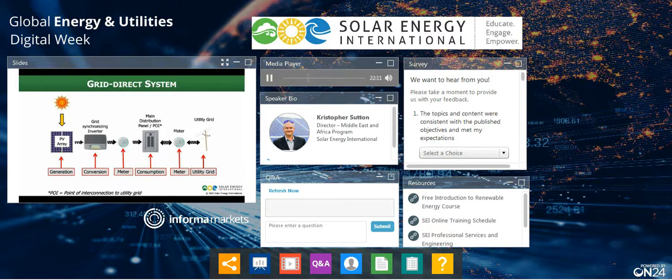The next thing that happens, we go DC from the PV array into the inverter. The inverter, when it sees AC electricity from the utility grid, will synchronize with it automatically. Once it synchronizes, which can happen in seconds because it's electronic synchronization, this is completely different than trying to synchronize a motor generator. A lot of people think about these things like a motor generator, like a diesel or propane or gas generator. And this is very different.